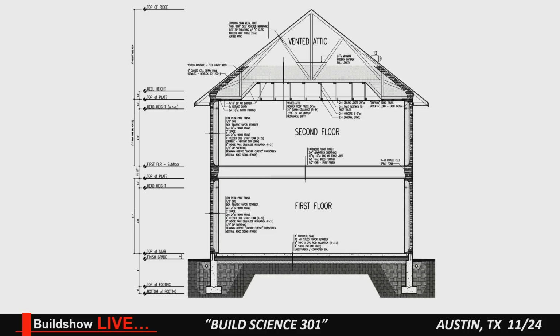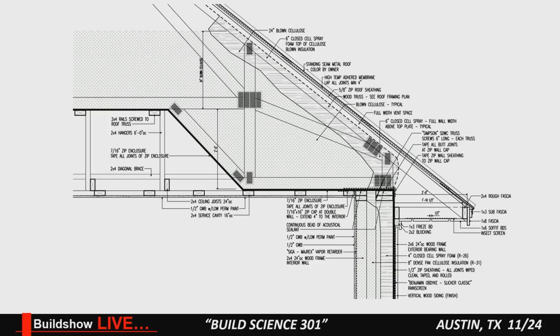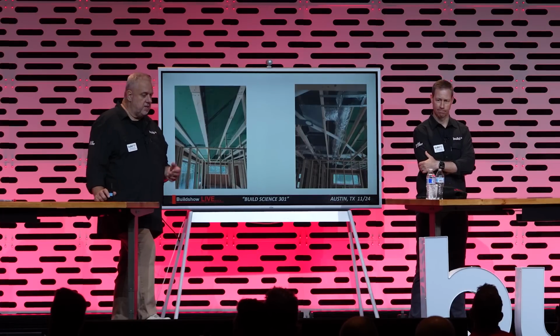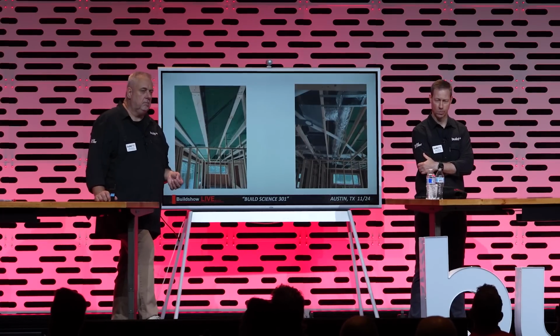We take that attic and we air seal along the contour of that attic, so now we can put stuff up there and we can deliver our heating and cooling system to every room on the second floor. We can deliver all of our ERV ports to every room on that section, right? It's called design. And then if you're looking for the detail, that's what the detail looks like. But basically understand that that air barrier is basically contouring that manufactured attic. That was really smart. And then you can see here, this is the example of the construction.